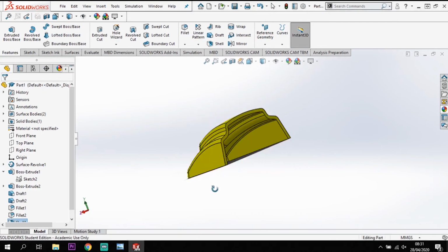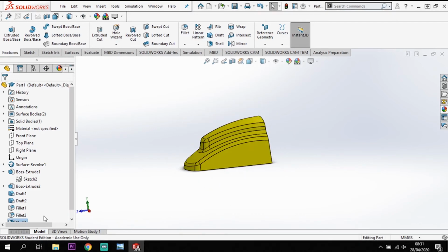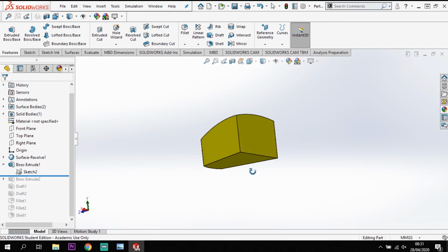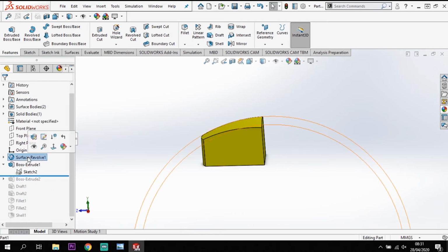Okay, so if I'm going to make these alterations, I'm going to have to pull this design bar back here. So I'm going to take it back to the point where I had my first fillet, or my first extrude up, sorry. Now, at this point here, I extruded to that surface there.